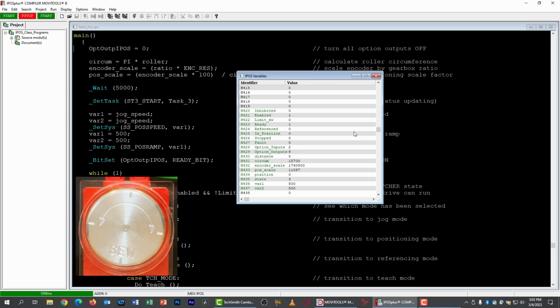There we go. All right, now we need to check the early exit conditions, and we have a number of them, so we'll have to check them one by one. We'll start with controller inhibit. Let's trip the go bit. And now I'm going to hit controller inhibit, and it did indeed stop it. And it did go back to the dispatch state, which is what it's supposed to do. Now I'm going to turn controller inhibit back on, and what will happen is dispatch should drop me back into referencing once more. And it does.